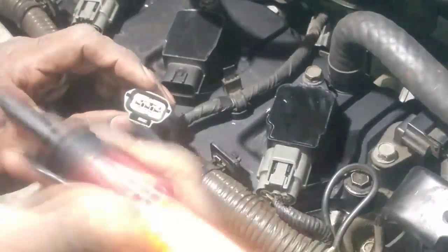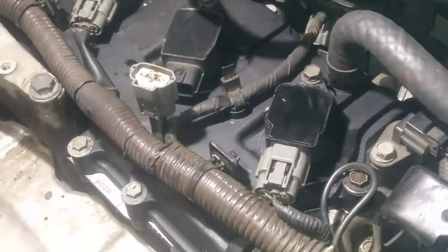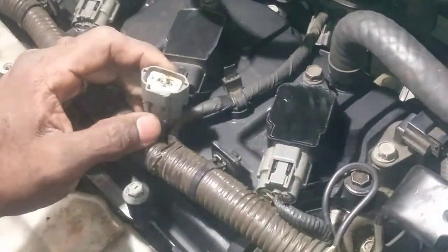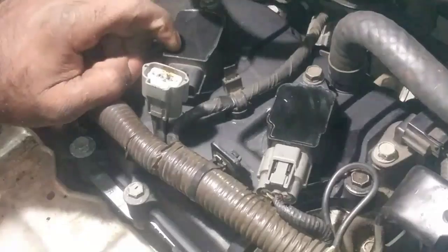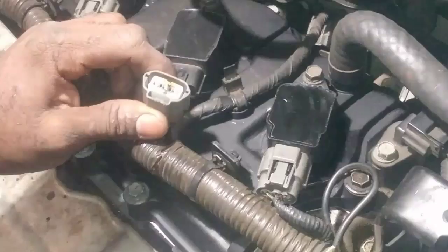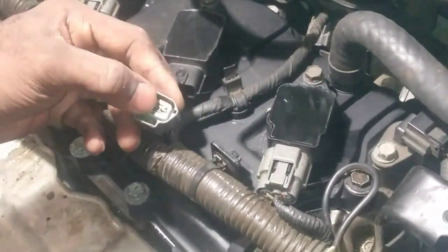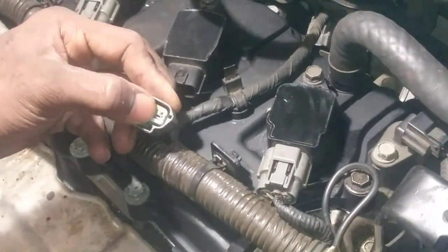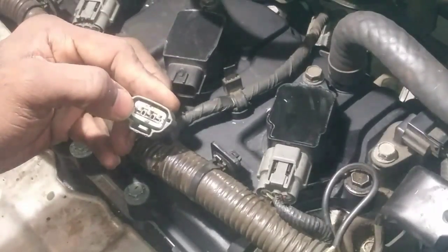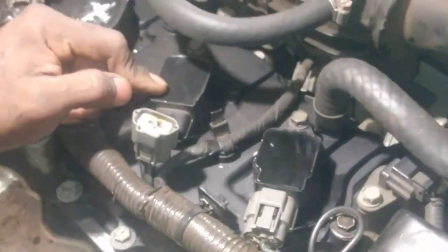What we're gonna do, I have my test light here. I'm gonna show you a real easy way of testing for ground, positive, and signal. So how this works is, this coil is internally controlled. Like on the Ford, you will have a 2-pin. This is a 3-pin. You have a constant 12 volt, a constant ground, and what only changes is that signal side, which is basically a transistor inside this coil, which allows rapidly switching signals.